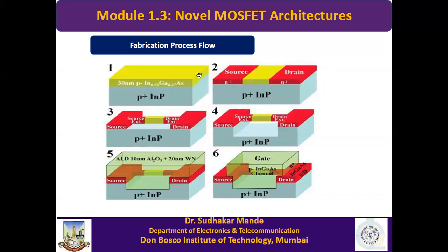Here this is P-type material. With some process, maybe not diffusion but ion implantation, we selectively change this much conductivity to N plus, and this much conductivity to N plus, and we call that the N plus drain and N plus source.